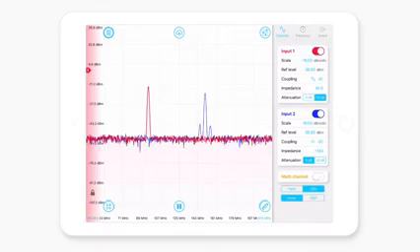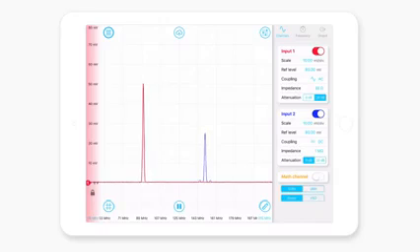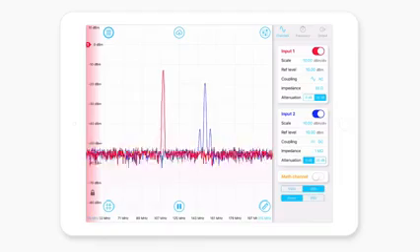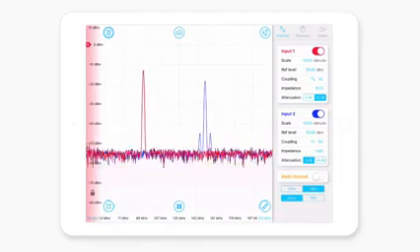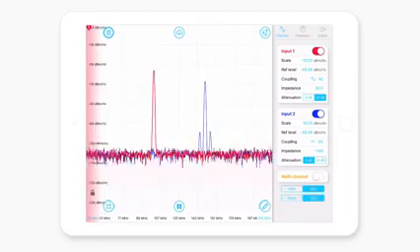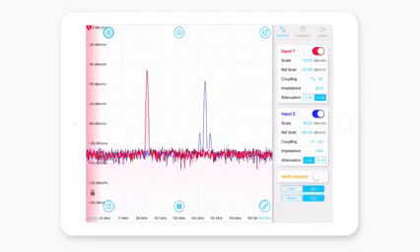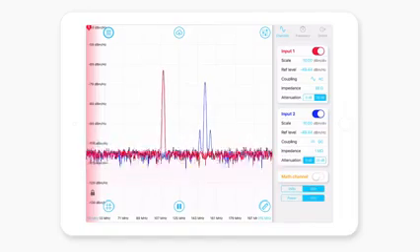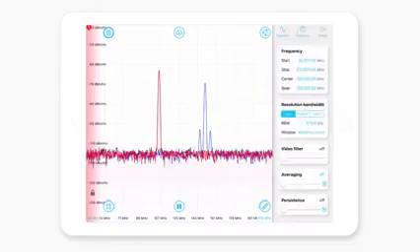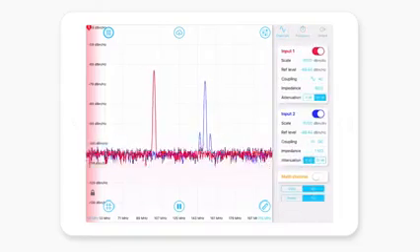The other thing that you'll notice down the bottom is that you can change the units in which you view data. So, we can look at it in a linear scale, so volts, and you'll notice that the noise is very low in this view, but most of the time you're actually interested in these small features, so you look at it on a logarithmic scale in dBm. But you can also view these traces in units of power or power spectral density. And so the power spectral density is useful because it basically normalizes the power to the resolution bandwidth, which I'll get to in a second.